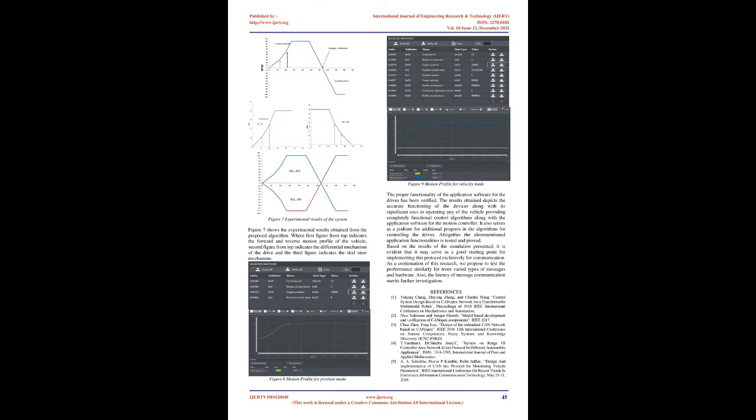B. Core concepts of CANopen. Communication models: master/slave, client/server, and producer/consumer. Communication protocols related to the models are various protocols used for different communication purposes, e.g. transmitting real-time data. States: each device supports different states. Using particular messages, a master node will be responsible for the state of a slave node, e.g. resetting it. Object dictionary, OD.